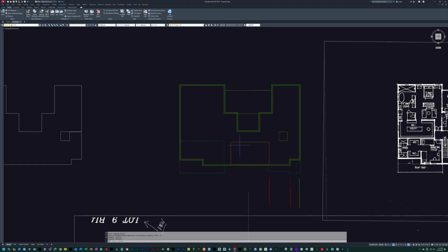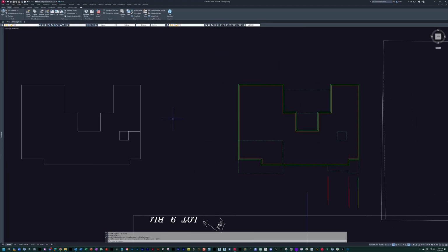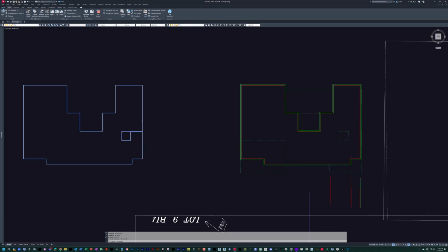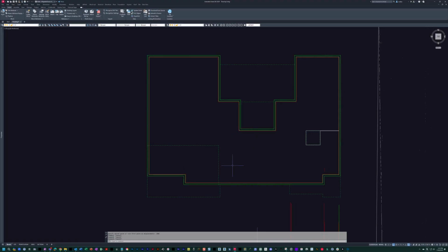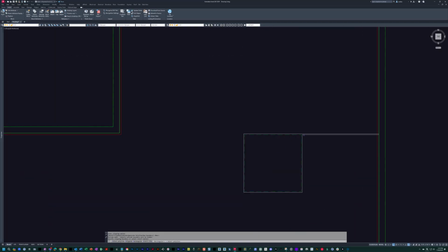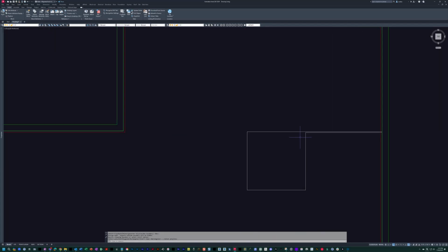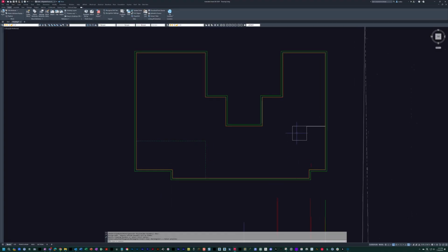So I'm going to delete that X clip, and I'm just going to move this guy up out of the way just for a second for demonstration purposes, because now if I move this guy back, and now if I X clip my ground floor and select polyline, now again it goes away, this all goes away because it's backwards.